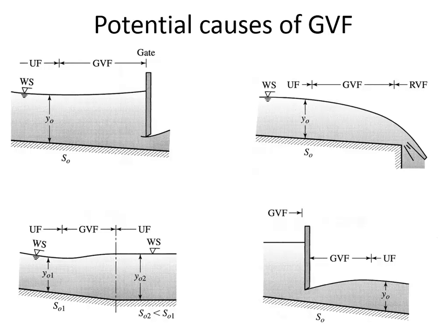It's just that here, in between these two sections, it's varying gradually because there's no hydraulic jump. There's no need for a hydraulic jump because it's going from one supercritical flow section to another supercritical flow section. So we only see the jump when there's a transition from super to sub. Does that make sense to everybody? Okay.